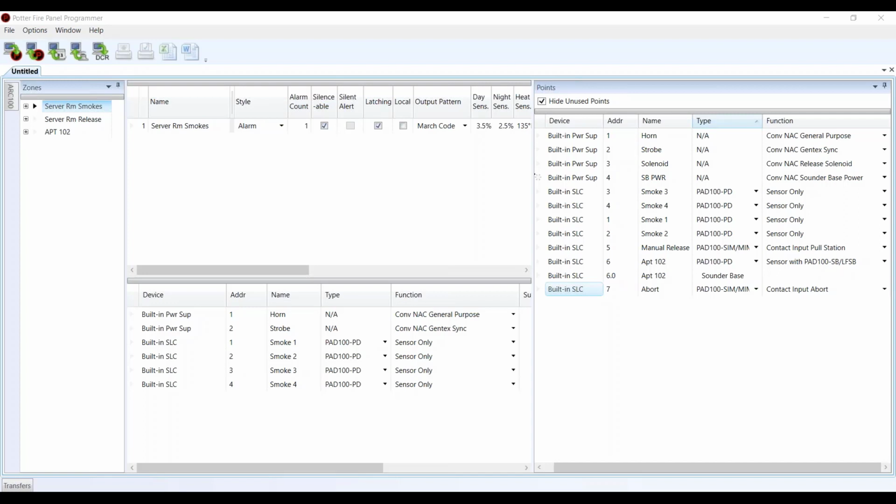If you're familiar, you can go through the keypad and activate point control and just put a point into alarm. If you wanted to test out your programming on a smoke detector, or test the alarm function on the heat detector, you can do that through point control, but you can't do a low temp test through point control. So you have to somehow drop the temperature on that detector. Good question.